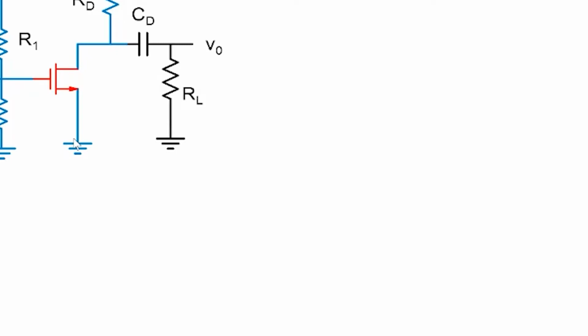And so when we see amplifier circuits like this, we notice that there are two kinds of voltages. There's a DC voltage applied, the purpose of which is to bias the transistor in the suitable region of the characteristics. And then, of course, there is the signal here. The signal can be an audio signal, a video signal, could be anything. But just for the sake of discussion, we'll be taking this as a sinusoidal signal. So there is a DC analysis, and then there is an AC analysis, or because the signal is small, we also call that the AC small signal analysis here. And so the goal is to calculate AV equal to V0 by Vs.